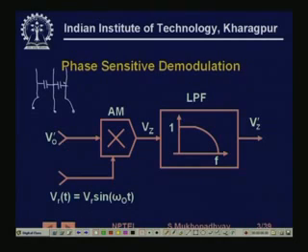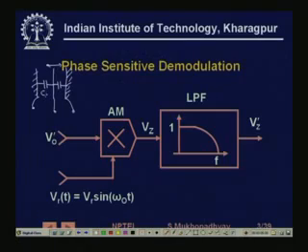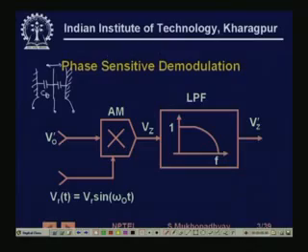These plates are fixed and this is the movable plate. As long as the displacement is small, both of them are equal in the nominal position, because the separations are equal. So, if it becomes C naught plus delta C when it moves to this side, then this one will become C naught minus delta C, right.